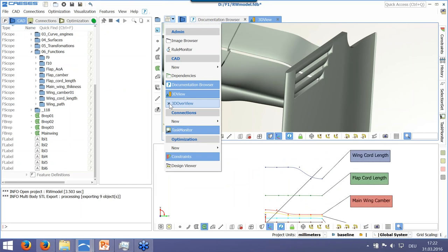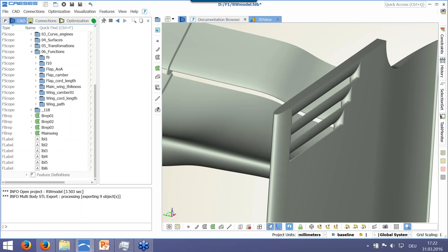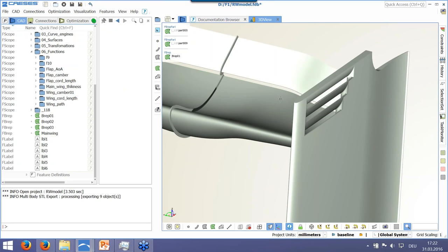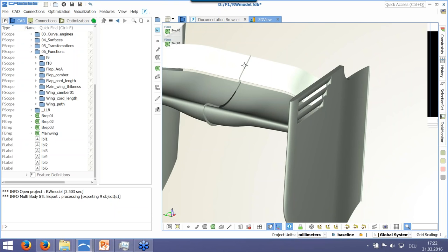All right, so you can see my screen now. Yes. Great. So here on the top side of the wing, in this region, the pressure is really high. Like we talked about last time, when you have a difference of pressure, delta P, and you have a discontinuity, like you can see here in this sharp edge, a strong vortex will be created. The flow in this region will try to escape to this region, because here the pressure is approximately atmospheric and here it's too high, so this flow will try to go this way and will create a really strong vortex.